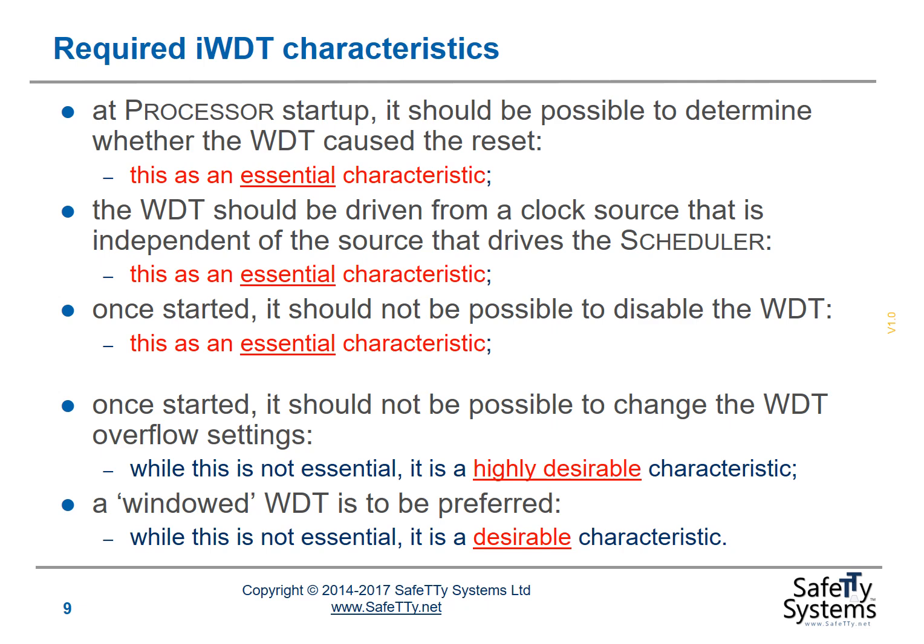A windowed watchdog timer is also a good solution. In a windowed watchdog timer, we check not only... we set a watchdog time, for example, of 2 milliseconds. We check to make sure that the watchdog is refreshed within an interval of 2 milliseconds, but we also set a lower bound on the refresh rate.